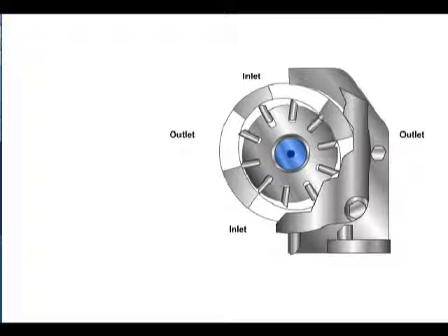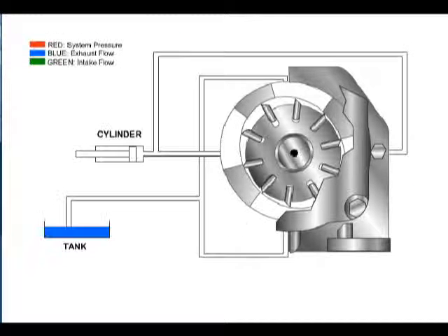With the forces acting on the shaft balanced, the shaft side load is eliminated. Flow is created in the same manner that you have seen illustrated in the unbalanced vane pump, the only difference being the two discharge and two suction cavities rather than one. It is notable that constant volume positive displacement vane pumps used in industrial systems are generally of the balanced design.